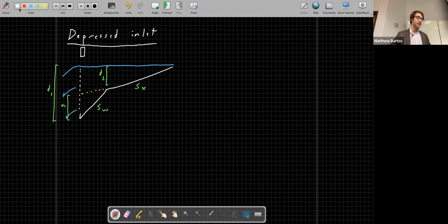And for the length of the inlet needed to capture 100% of flow, it's essentially just an adaptation of the previous equation where we use a different slope now instead of S sub X. Okay, so the length of the gutter needed to capture 100% of flow is KU over N times S sub E, I'll talk about what this S sub E is. So this used to be S sub X, our cross slope. It's now what's called an effective slope, all raised to the 0.6 power times Q to the 0.42 power times the longitudinal slope to the 0.3 power.